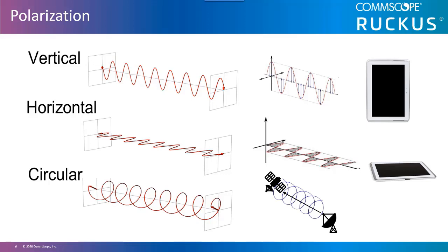When using this type of antenna, you will want to point the coverage where the intended receivers reside versus pointing the tip of the antenna at them as if the antenna were some type of magic wand. This type of antenna has a coverage pattern that resembles a donut or a bagel in shape. So if you point the antenna at a receiver, you are pointing the hole at the receiver and not the RF coverage. The technical name for this type of coverage is toroidal.